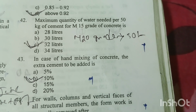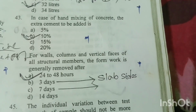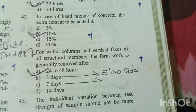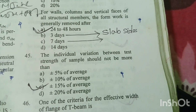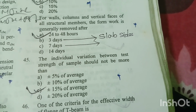Question number 43. In case of hand mixing of concrete, the extra cement to be added is 10%. Option B is right answer. Question number 44. For walls, columns, and vertical faces of all structural members, the formwork is generally removed after 24 to 48 hours. Option A is right answer. Question number 45. The individual variation between test strength of samples should not be more than plus minus 15% of the average. Option C is right answer.